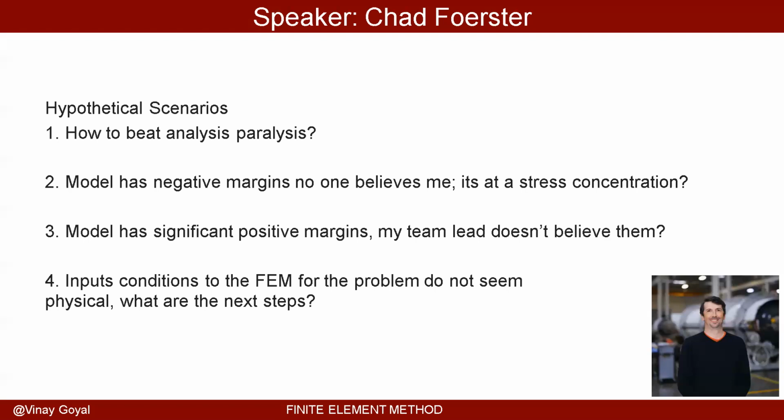And I will be honest, I'm a culprit of that. I'm saying that's not real. To be honest, it is real for that model, but that doesn't mean that model is right. And so I think having an honest conversation about what defeaturing tactics were used in the model, globally and locally at that area in question, is very important for informing a decision, because we know through our studies and final modeling that certain features will produce these kinds of hot spots, and we have these rules of thumb like, well, you can kind of ignore that.